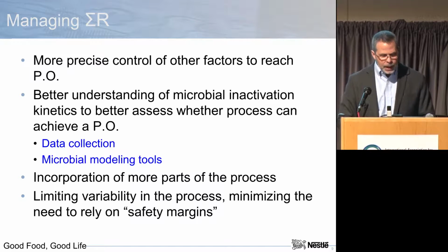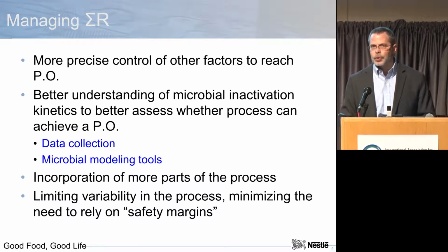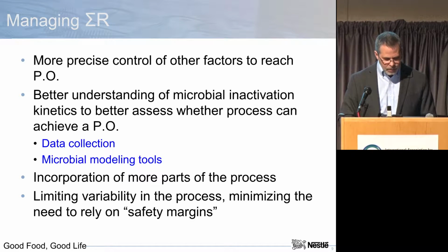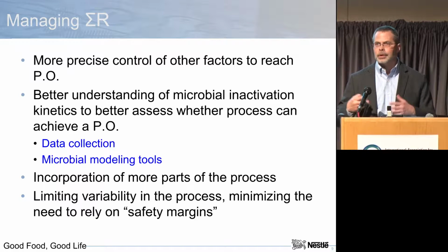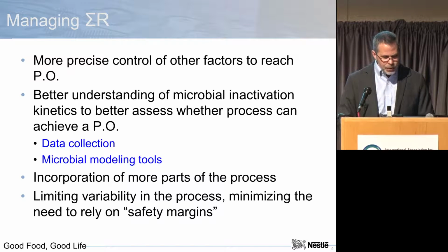I can manage the increase due to recontamination through environmental surveys and history, and I can also, of course, manage the processing environment to make sure that I don't have points in my environment that might increase the risk. This may be just environmental controls. It might be a UV filtered or HEPA filtered filling zone to make sure that I'm not adding my hazard at the point of filling. So there's things that I can maybe do to manage recontamination.